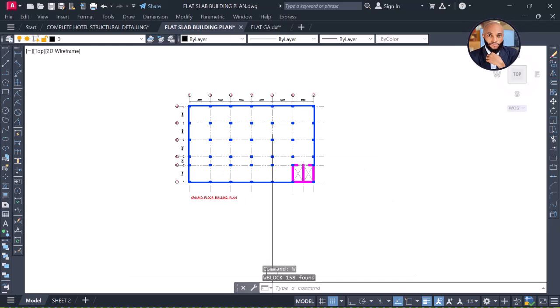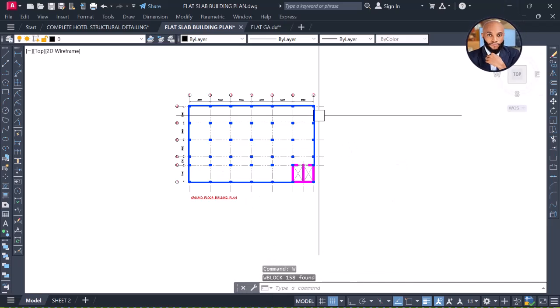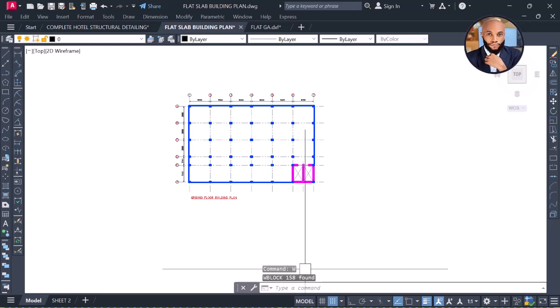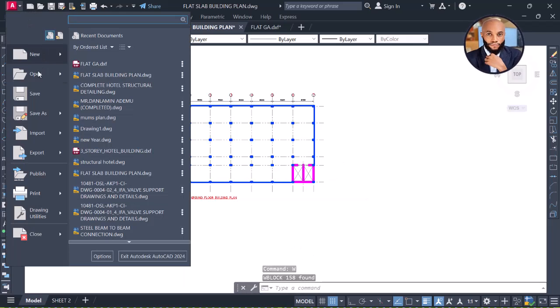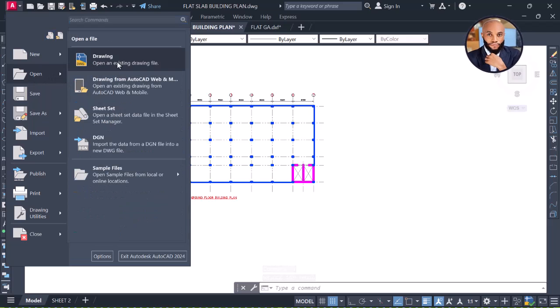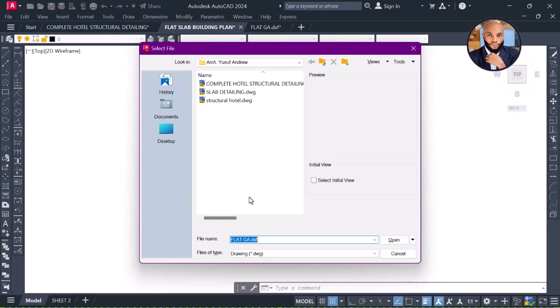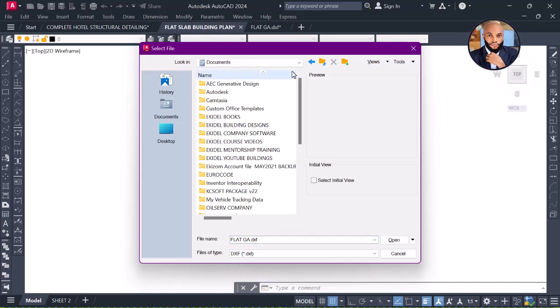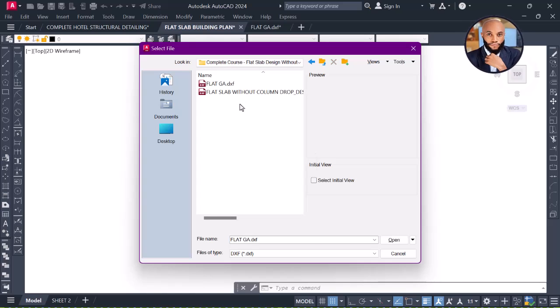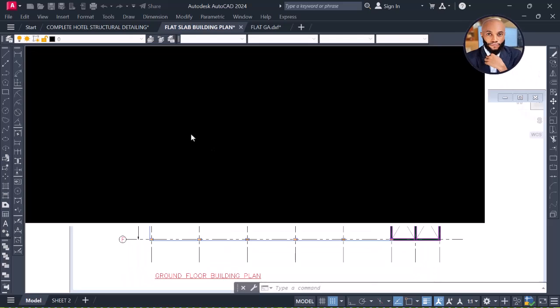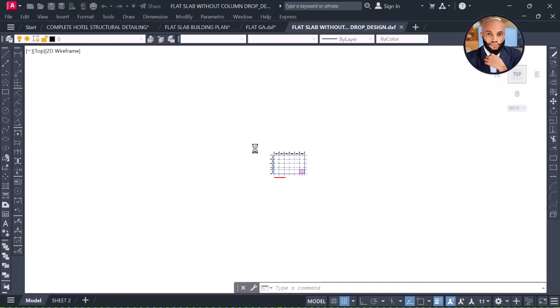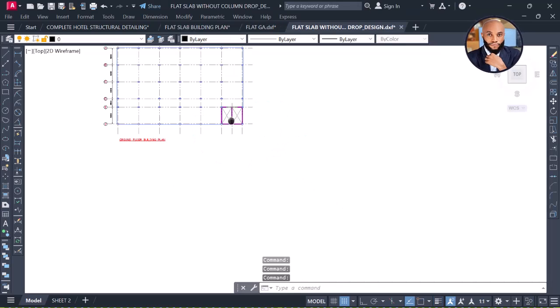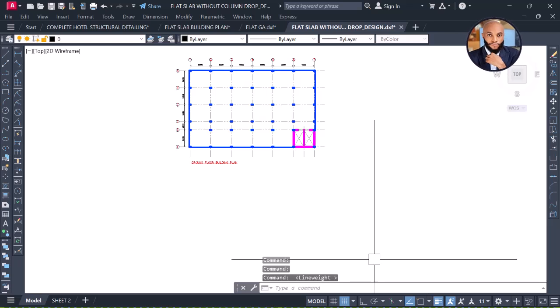So on this okay now, once I've done that, the next thing we'll do now is to go and open up the software in AutoCAD. Open up that DXF file again. Let me just go here and then click on open here, open. So if I click on open right now, I'll change here to DXF, and then locate where I saved the file, because we are meant to save that drawing. Yeah, open this one right now. Now on opening this drawing, you can see what we have here. We have this drawing here. I'll just turn on my line weight, and then you have this.